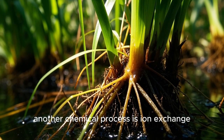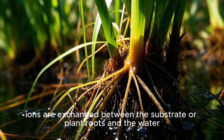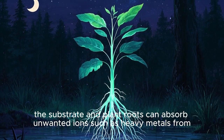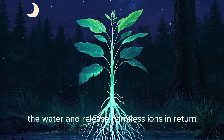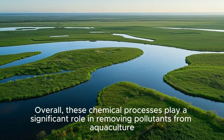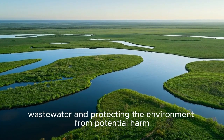Finally, another chemical process is ion exchange. During this process, ions are exchanged between the substrate or plant roots and the water. For example, the substrate and plant roots can absorb unwanted ions such as heavy metals from the water and release harmless ions in return. This can help remove heavy metals and other dissolved contaminants from the water. Overall, these chemical processes play a significant role in removing pollutants from aquaculture wastewater and protecting the environment from potential harm.